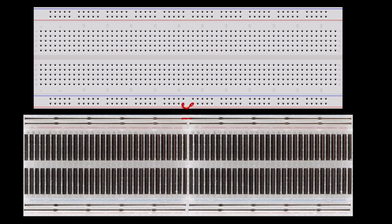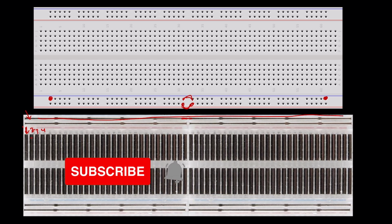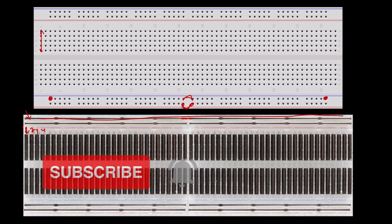Now if you give a connection at this point, then you can access the whole power rail. That means from this point to this point, all of these points you can get the connection. And here you can see in the component line, this is line 1, 2, 3, 4. Line 1 and line 2 are not connected together, but in line 1 all of the points are connected together. That means if I connect a resistance at this point and at this point, those two resistances are connected together.